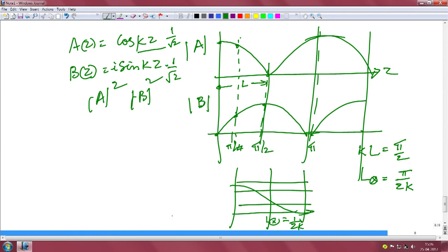In conclusion, we can say that the directional coupler is a very useful device. I would just like to mention that in optical switches we can change the delta in the refractive index by using external fields, and we can switch between the crossover state and the bar state by using external electric fields. We will come over to these after a few more classes. Finally, to summarize, the directional coupler is a device that can be used to exchange power between waveguides, and there are many applications. Thank you very much.